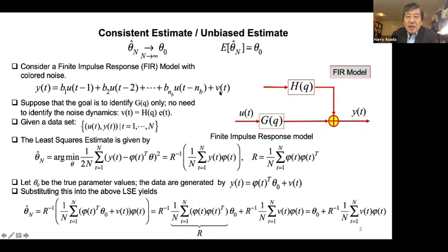So in this case, an FIR model, we have a mainstream from input to output. This is the main transfer function we'd like to identify. In the case of an FIR model representation, this is represented as a moving average, basically an impulse response type of representation: u(t-1), u(t-2), up to u(t-nb). That's a kind of moving average of the input time sequence.